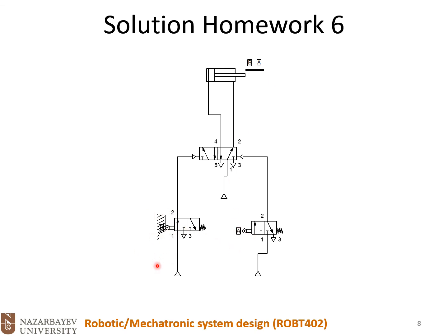So for example, here you see that the Festo fluid sim is putting this wall or mechanical barrier here on this roller. So it means that this roller is activated by the sensor B at this time. Okay, so once the rod moves forward and reaches sensor A, then you will see this symbol on this roller instead of the other one.